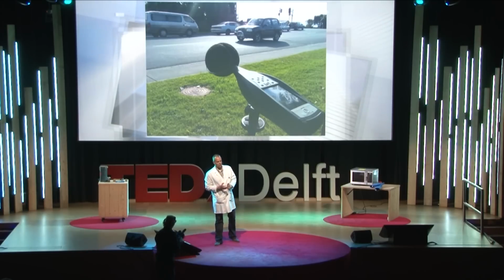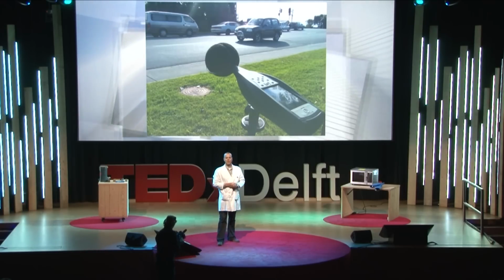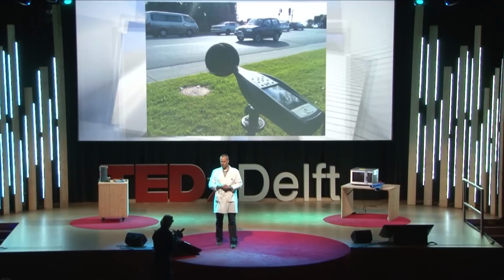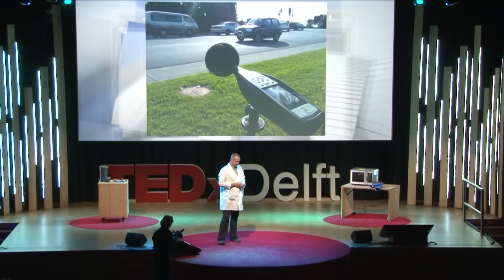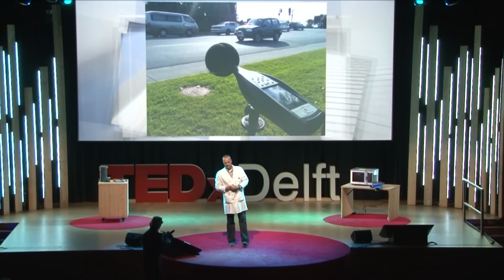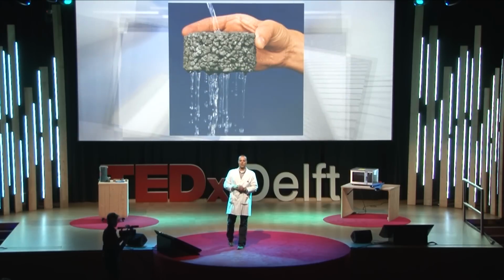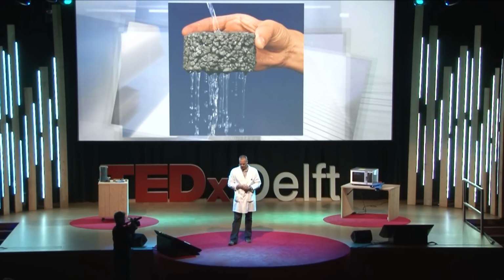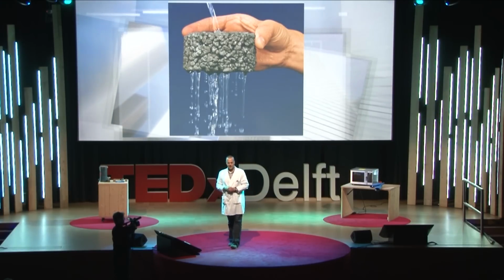Also, asphalt can create a lot of noise. It's a noisy material. And if we produce roads, like in the Netherlands, very close to cities, then we would like a silent road. So we have solutions for that. The solution is to make roads out of porous asphalt, a material that we use now in most of the highways in the Netherlands.